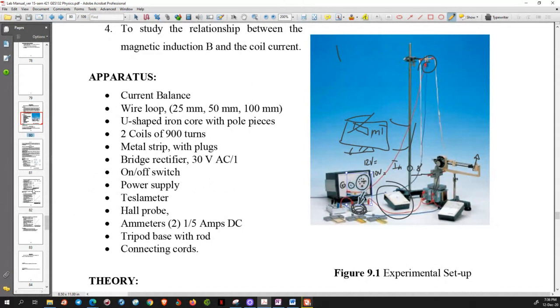Teacher, can you repeat how can I find M original? M original? Yeah. Connect the circuit without turning it on. But then you have to balance here to 0. Whatever is the value, that's the M original. Okay?